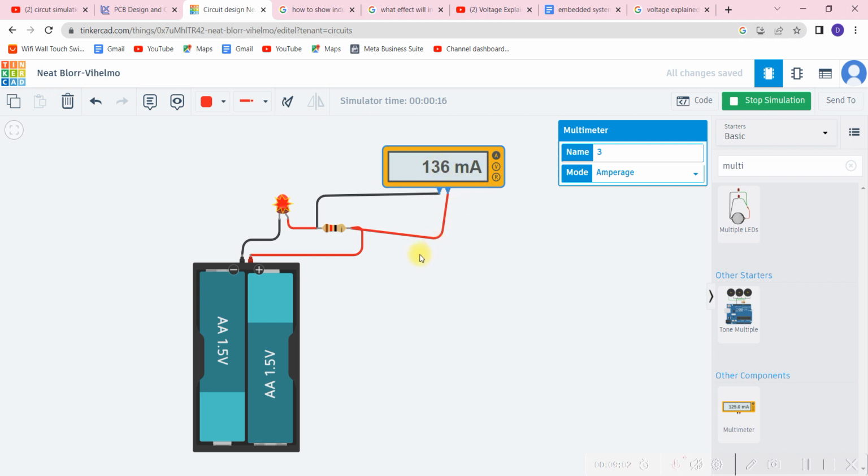Or actually, from what I've seen, this LED actually ended up blowing. Okay, I know why. That's weird. The LED ended up blowing because when I switched my ammeter to current mode, what actually happens is that this ammeter creates another circuit within itself, so it bypasses its resistor completely.